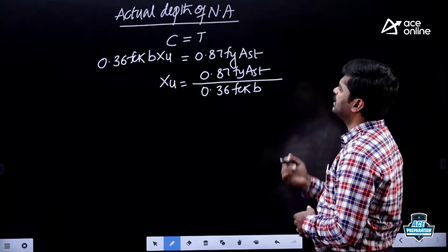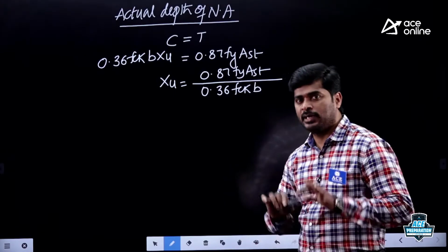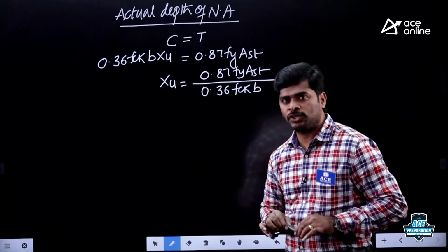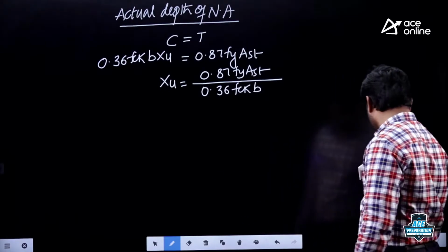Then what is the concept to find out actual depth of neutral axis? Simply equate compressive force to tensile force. You will get actual depth of neutral axis. Now we will take one question.